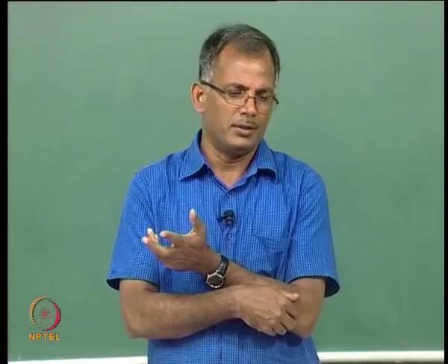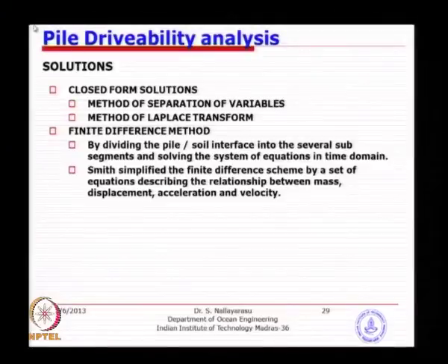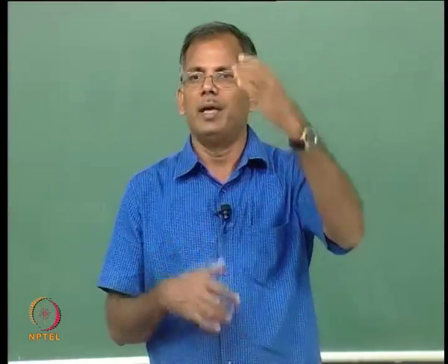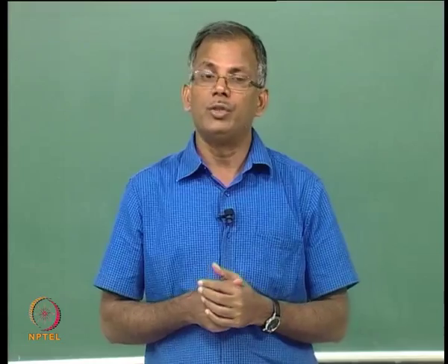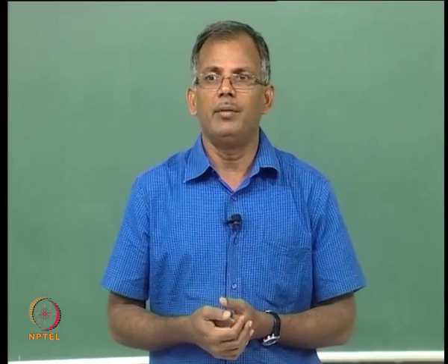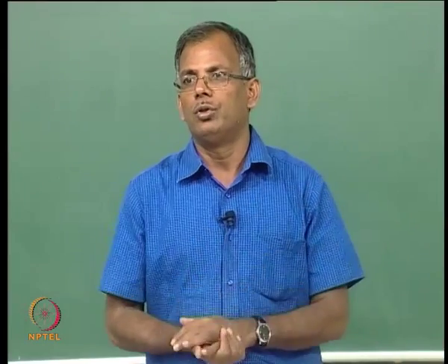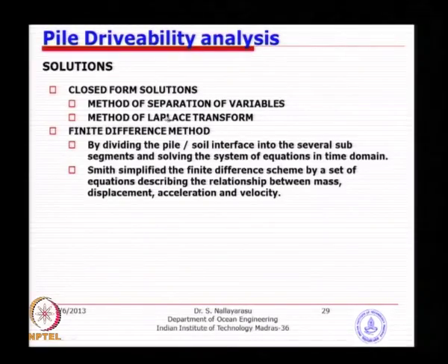We will have a look at it when we get to that stage, but otherwise most of the time we use the numerical scheme because of the complexity of the system that we have. We have a hammer, we have varying pile segments with different soil, and we also need an accurate solution because the complexity for offshore projects is slightly more compared to onshore. So, we do not want to use dynamic pile driving formulas, neither do we use the closed form solution because it makes too many assumptions that may not fit our systems.